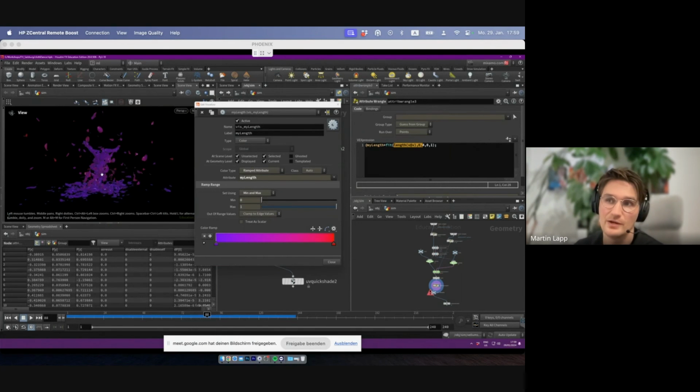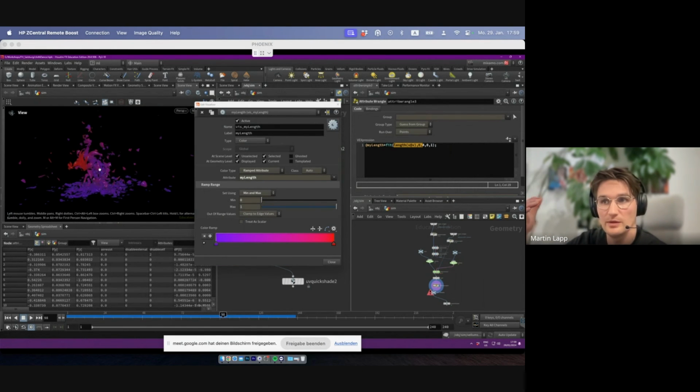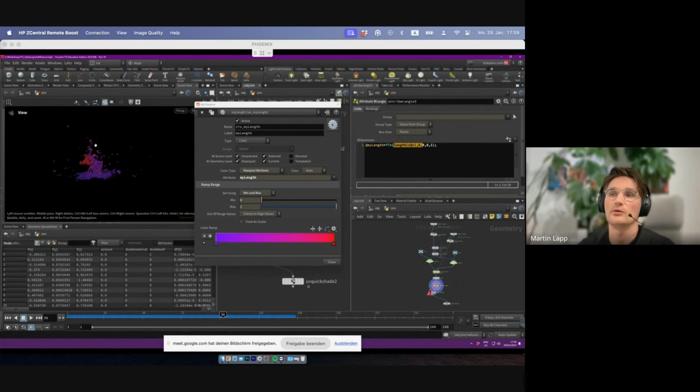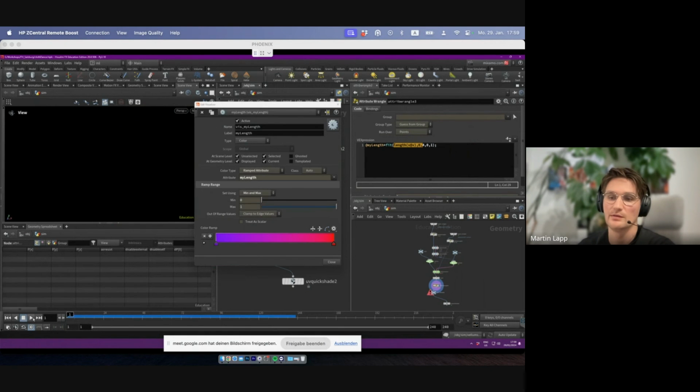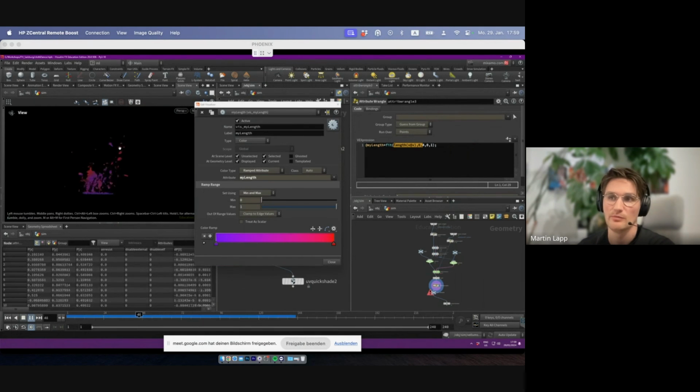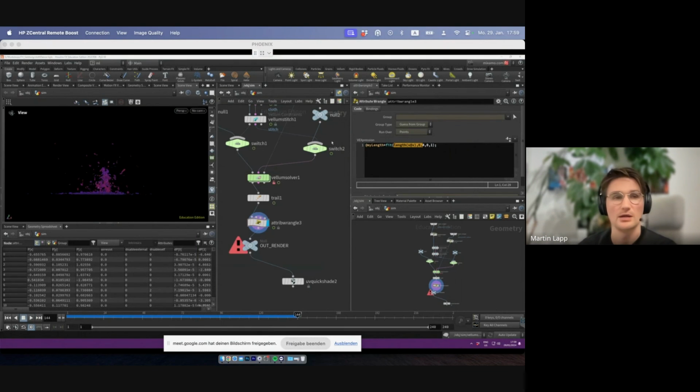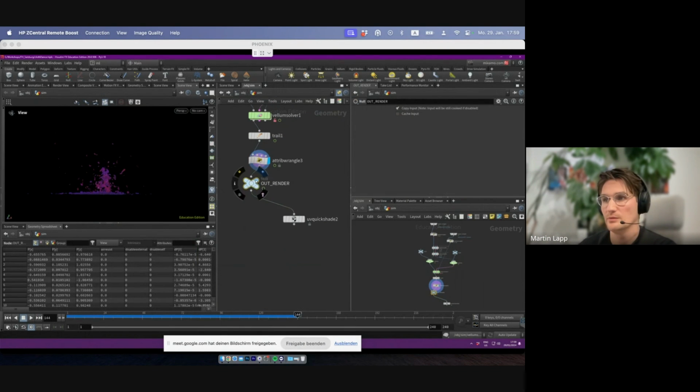Everything that gets freshly born, like here on every 10th frame, is turning red because the initial velocity is quite high, right? That's why it's exploding. And also, generally, the velocity is higher at the top because of my pop wind. My pop wind adds this turbulence that is multiplied by the velocity. And that is the reason why this attribute looks like this.